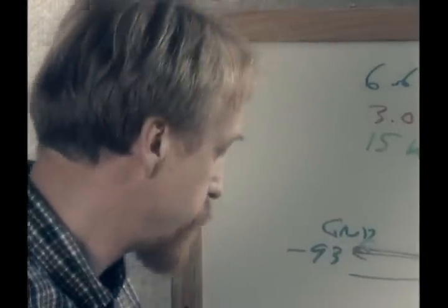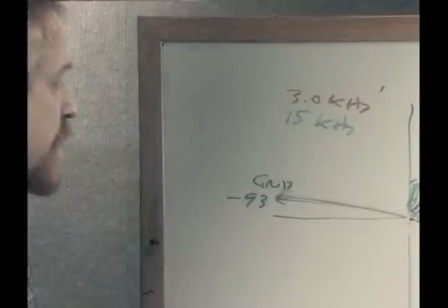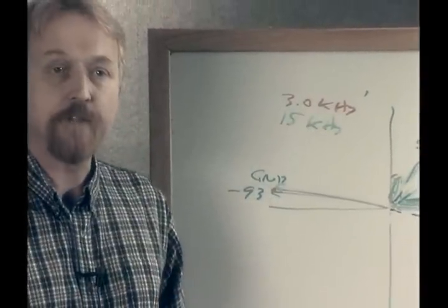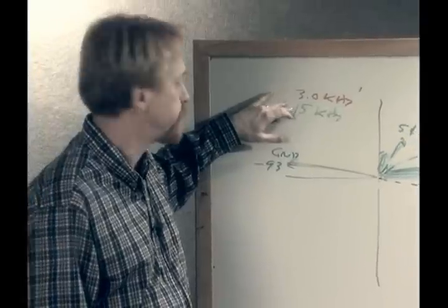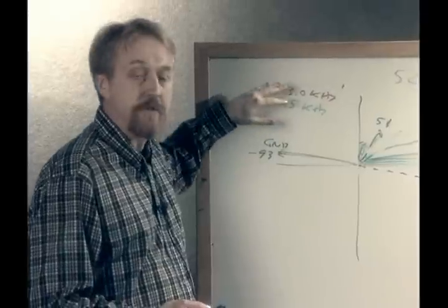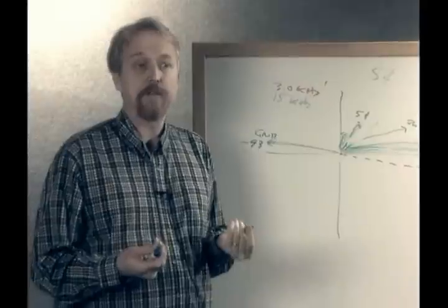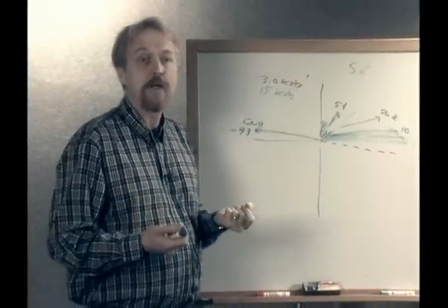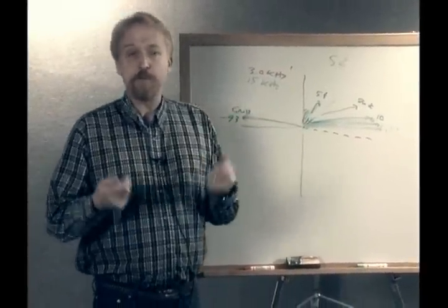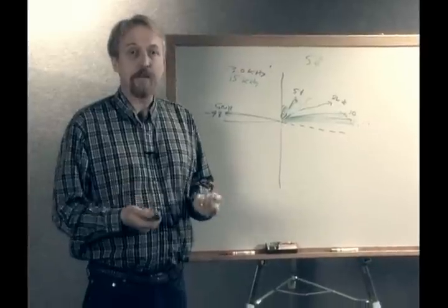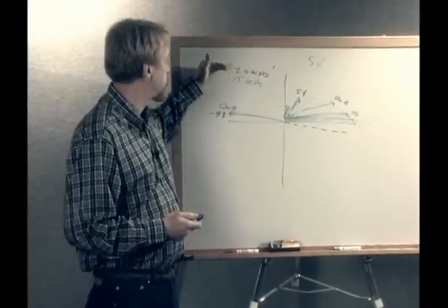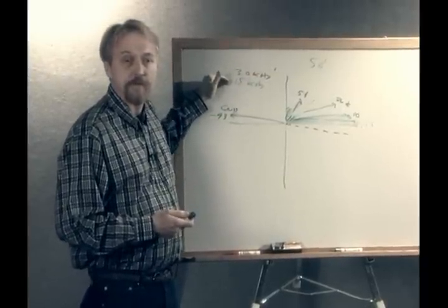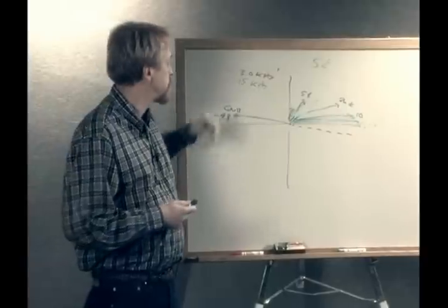Okay, now this brings me to the DFX and what specifically it offers in the way of new features and capabilities. The DFX transmits and receives simultaneously at these two frequencies, 3 kilohertz and 15 kilohertz. And what makes it unique is we have each of these frequencies available independently, and we can select either one and process signals in the manner in which we've successfully done it for many years by doing ground balancing, discrimination, etc., at either frequency. So the operator can select whichever one he feels is more appropriate for the kinds of targets he's looking for and the ground conditions and such.